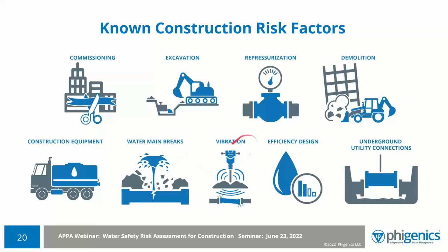I think it's very familiar to people. Vibration has been associated with healthcare construction. It could be another building type, but it wasn't reported in the literature. But vibration occurs when you're doing pile driving, foundation setting, jackhammering, saw cutting of piping. You can loosen biofilms and have them go downstream to an unsuspecting department where you have a vulnerable population, creating disease cases or deaths. Many folks are designing for water efficiency, but they don't think of water safety. The program is not sustainable if it's not safe.